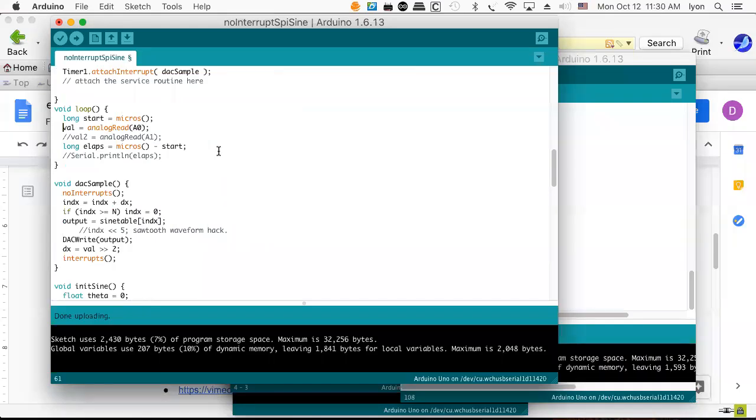And so then what that's going to do is it'll keep that value up to date. You'll be able to use the value when you proceed to do things like set DX. And so then in theory, the only thing you have to do to switch from the manual analog read, which runs however long it runs, to something that runs only when it's done converting, is you would comment something like this out.